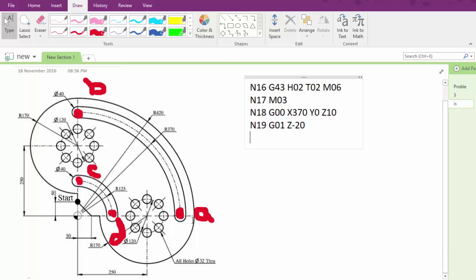And now we are totally engaged here in the slot with the required tool T02, and it's required to machine this path, so it's a counterclockwise direction milling here. G03 to point X and Y using center identification of I and J. These points have an X of 0 and Y of 0, the radius 370.